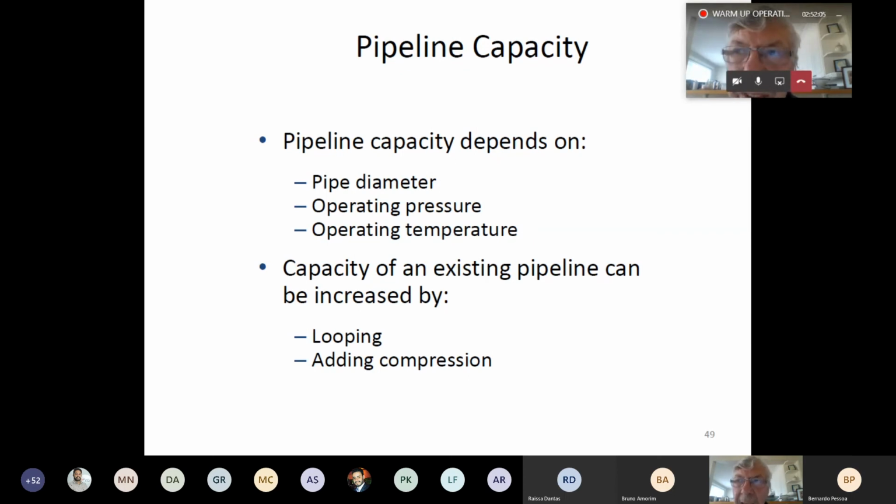The second option, when the flows are really increasing, is to twin the pipe. And you can do that with natural gas because the fluid itself is always the same, no matter where it's coming from. It's treated as it comes out of the different processing plants. It's 98% methane. And so that means you can have parallel pipe. They can interchange with each other. The fluid can mix, and it's all the same product. So it's very easy to loop and increase capacity by looping on natural gas.